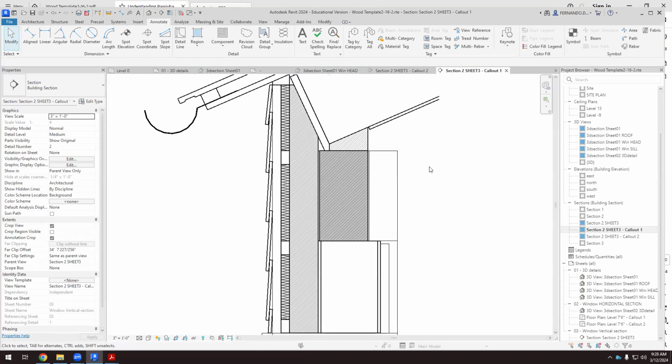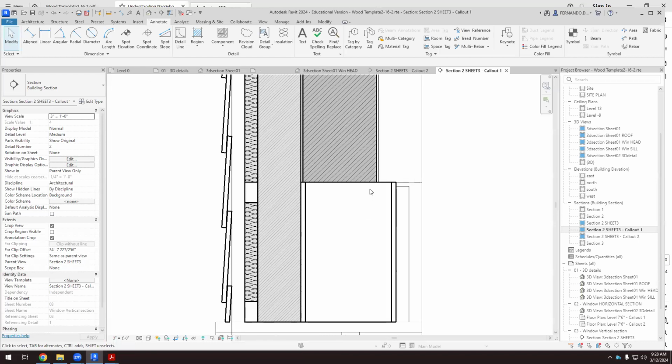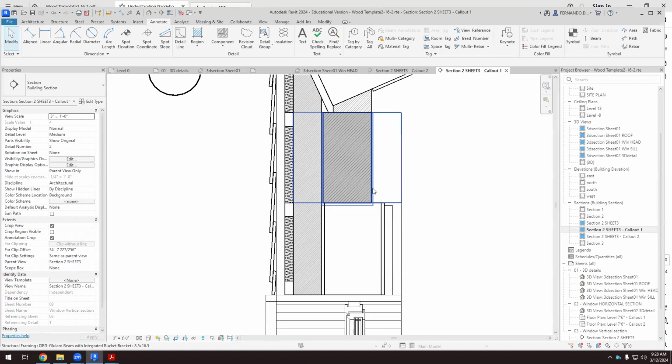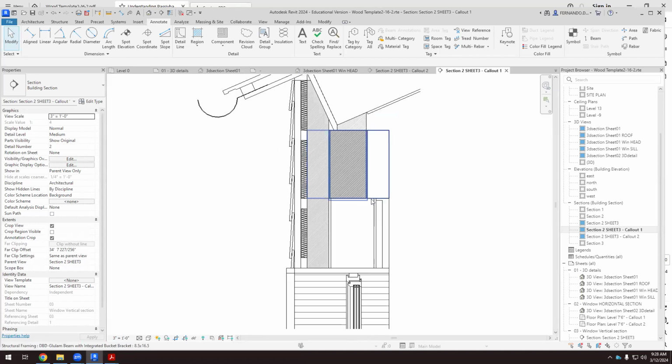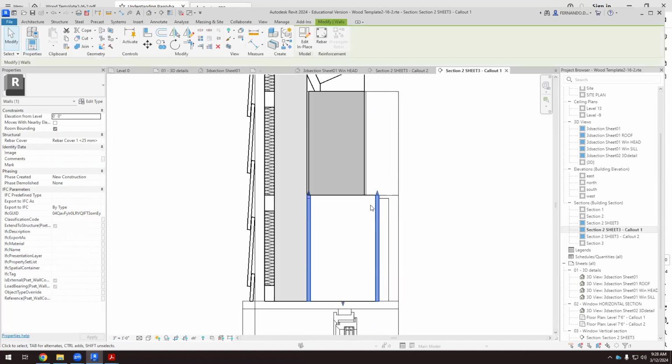Okay, so now there's a hierarchy of gray things. The darkest is the structural element. Then we have thermal insulation, it's grayish, the lighter and yellow one. And we have two different kinds of thermal insulation, so the hatch of the thermal insulation should be different. This is cellulose, by the way. So we have to apply the cellulose here.